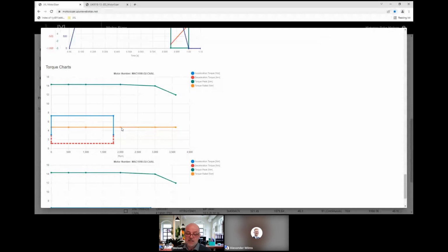Very interesting, because this is continuous torque we are here, and when we accelerate, it goes up like this, so you're using more than 100% torque in the motor. When you decelerate, you use less, that's correct. But because we are running only a little time, then we have a long pause, it's okay to run at 150 or 200% torque for a shorter time. Normally we say we can run 200% for about 10 seconds. We can run about 300% for about 3 seconds.